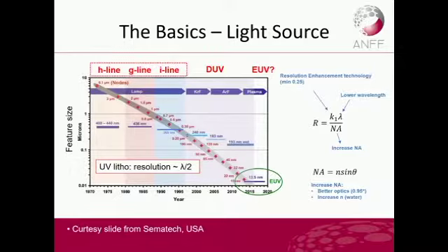I will not go much deeper into double patterning, but basically what it does is use your existing patterns and coat the sidewalls, and then do another exposure, coat the sidewalls, etch, and repeat once, twice, and 3 times. So each time you scale from 32 to 22, 22 to 15, 15 to 10, you add 25 extra steps in your lithography process. And that costs a lot of money for them to push.